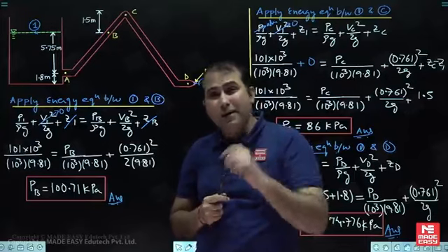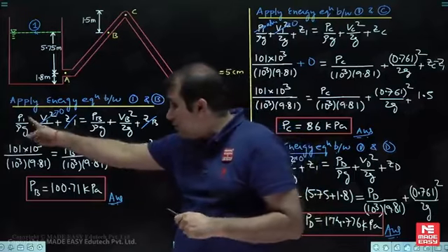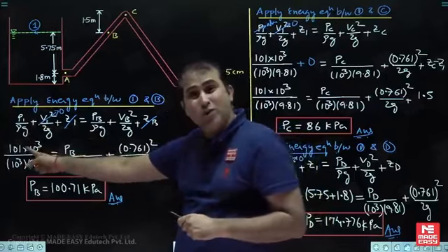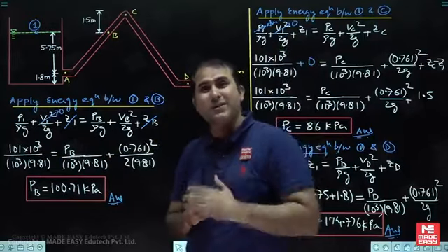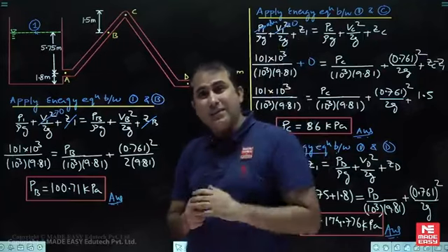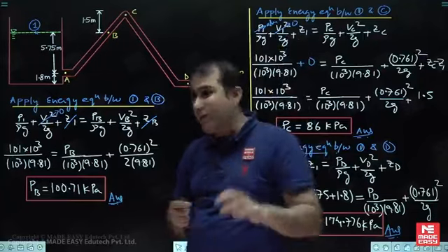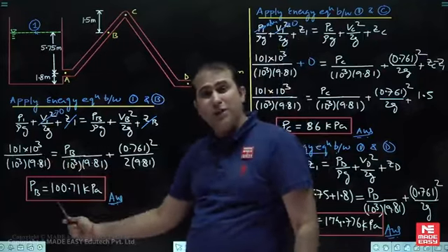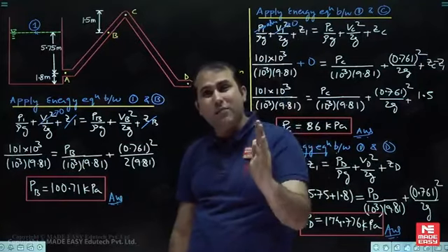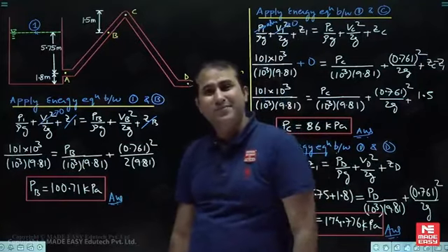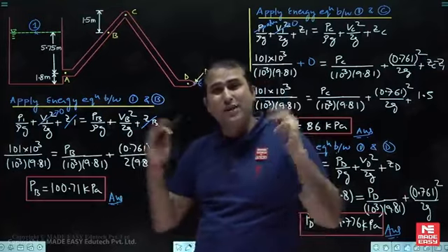My dear, अगर आप यहां पर गेज वैल्यू रखते तो गेज वैल्यू here is equal to what? 0. तो फिर जो प्रेशर्स आपके आ रहे होते, that is in the what? गेज. लेकिन since they have given the atmospheric pressure value, we have taken it here. So all the pressures, whatever we have calculated at A, B, C and D, those pressure values are in absolute. So this is a very, very special point here.